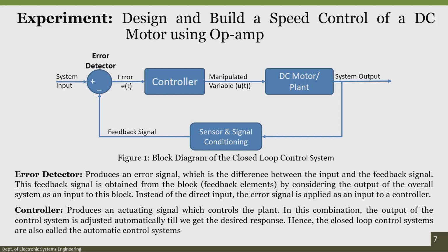So, to protect the motor from higher voltages, the output of the controller is connected with a Zener diode of voltage 5.2 volts. Even though the controller provides an output voltage higher than 5 volts, the Zener diode can regulate and limit the maximum input of the DC motor to 5 volts.